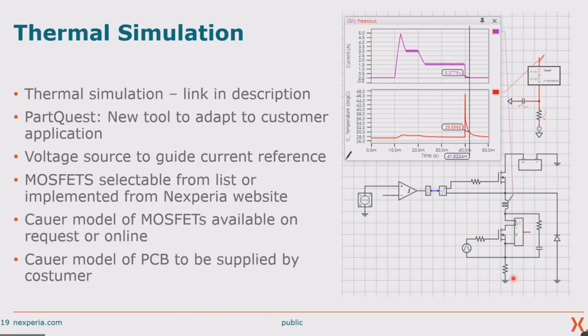All right. Then the next question, what is the diode in parallel to the inductor doing in the avalanche mode circuit? Nando, do you want to answer this one? Yes, sure. We can go back. This slide will do. So the diode allows for the repetitive avalanching event to take place.